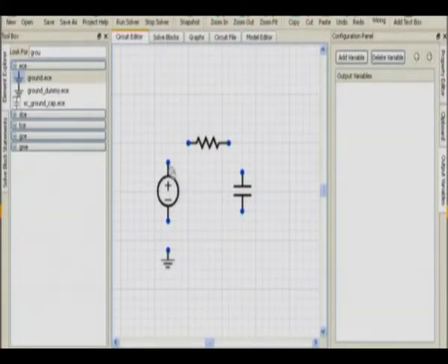All right. The next step is to complete the wiring. So click on one of the nodes, and then you will see a crosshair. If you want to introduce a bend, just do a left click there, and then click on the node where you want to end it, and then the wire will show up. If you make a mistake, suppose you want to get rid of this wire, you can just press escape and it will go away.